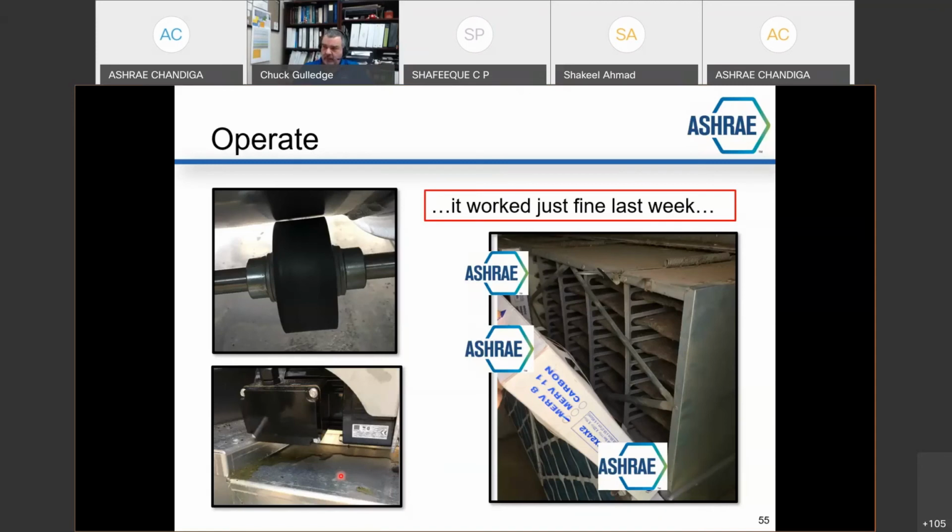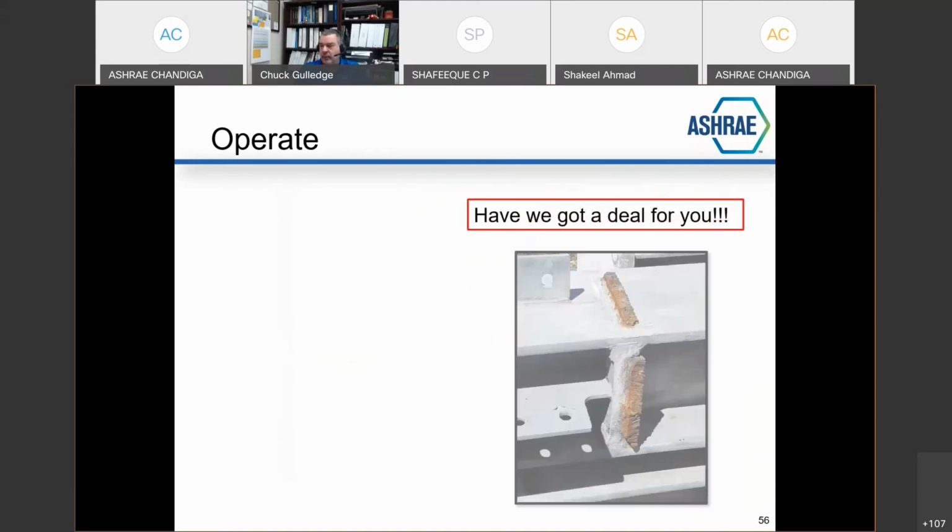And then we went back and looked at the equipment, and we found all these filters completely clogged, completely dirty, the desiccant drum not able to turn because it wasn't getting traction on the rotating wheel that turns the drum, and the crank that actually turned that shaft was leaking fluid. So this baby was in horrible shape. Lesson learned: make sure stuff is in good shape and does what it's supposed to do if you're repurposing it to do something else.